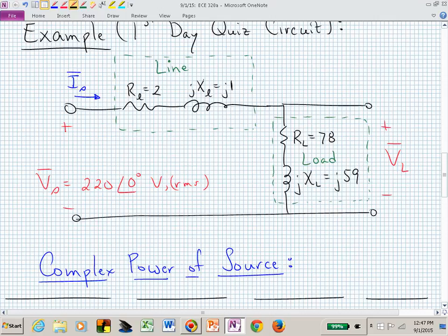Now the impedances are given. If we solved for I in our expression that relates V and Z and I, the I will automatically come out in RMS units, because of Ohm's law. V is equal to Ri. We are generalizing that now to have complex voltage and current. We now have V is equal to Zi. If V is in RMS, I will be in RMS.